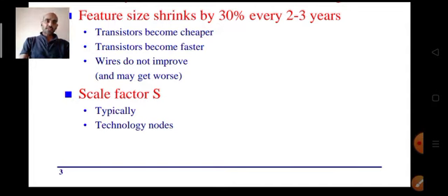As we have already discussed, the device length and width will get shrunk by 30%, because if previously the area is A, and later on you want the area to be 0.5 A, a 50% reduction. Okay, so then what will happen? To accommodate twice the number of devices, obviously you have to reduce the device area to half.